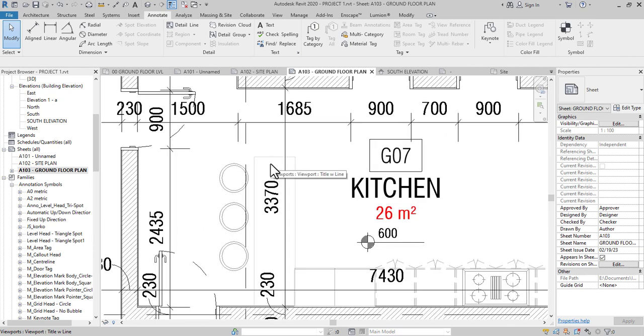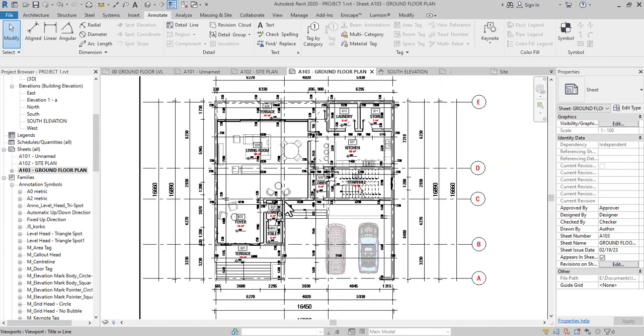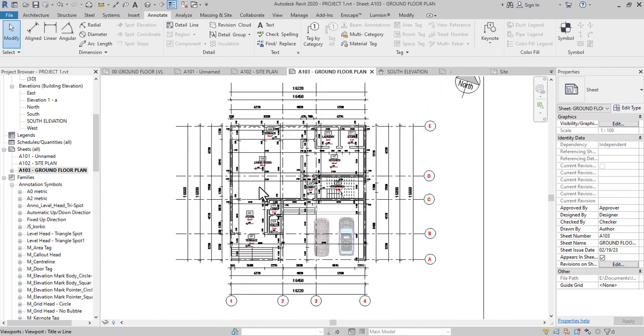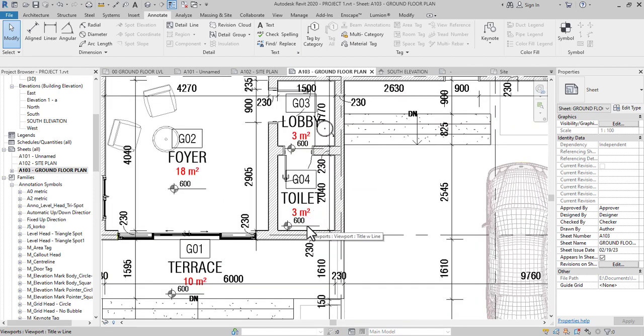Then, so this is our bachelor pad coming up good. We'll put our section lines eventually, and all call outs and all those stuff. Start to get flesh. Then if you really want to be thorough, I'll put the toilet before the next class. So if you really want to be in depth, very detailed about it, after your coordination, you also want to maybe show all the penetrations through the building. So that is a different layer, or that's a different set of working drawings entirely, where you will show all the penetrations, plumbing, electrical, mechanical, on the floor and on the wall.